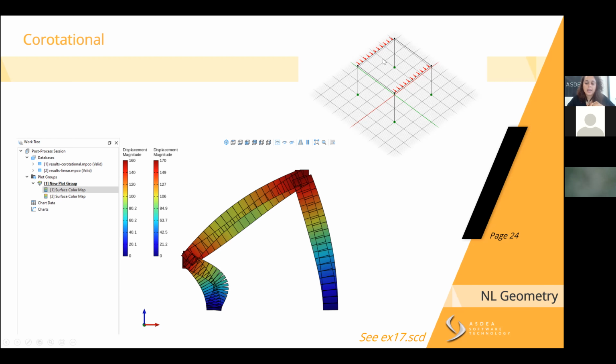Of course, this is a borderline condition, so we're almost never really at this point in our structures. But if we're pushing our structures a lot, for example, if we're doing a pushdown analysis of the self weight to see what's the ultimate resistance, then we need to take into account that the geometry of the structure changes throughout the analysis. So for today, I'm finished.